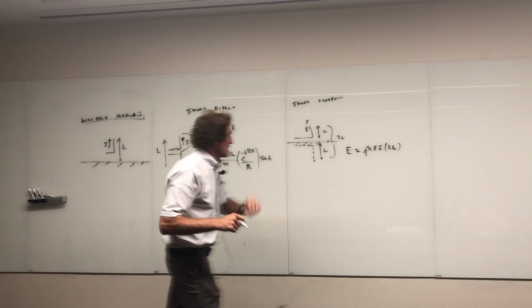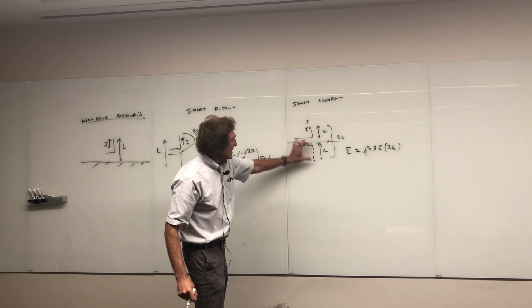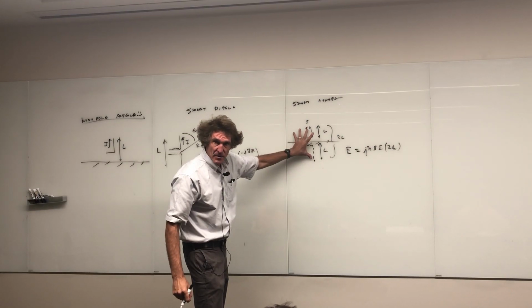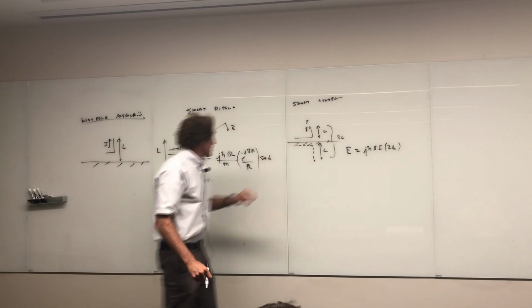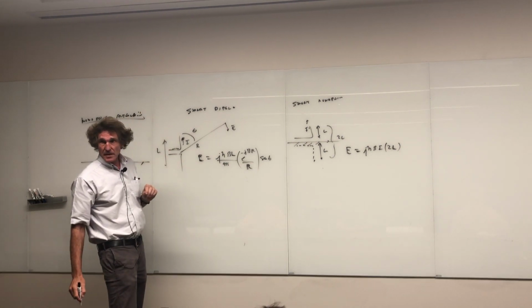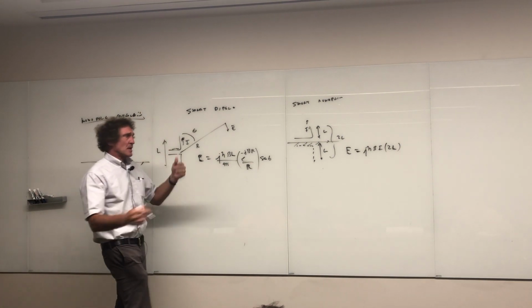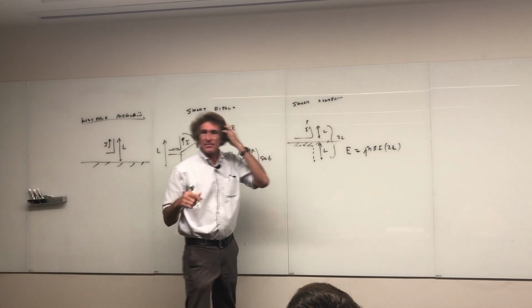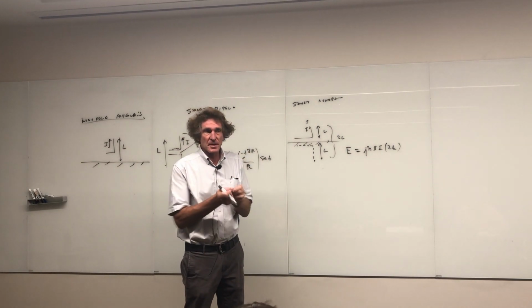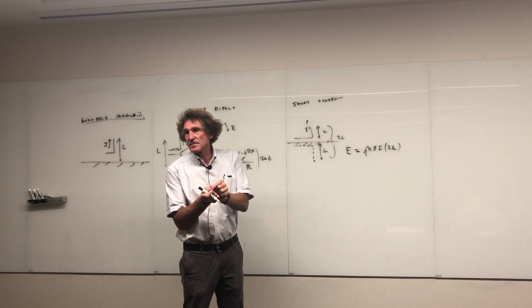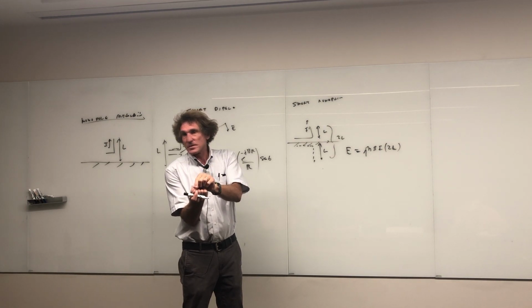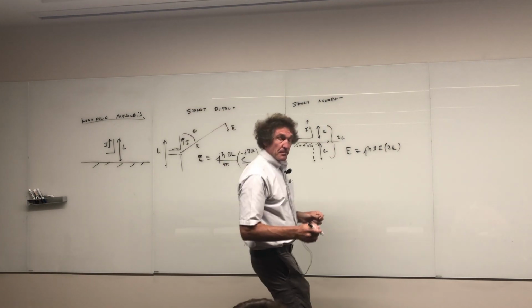It's the length of the antenna, and because the monopole has an image down here, the total length is 2L. Here, the length is just L, the length of the antenna. No, that gap's infinitesimally small. Normally, they assume that when you drive an antenna, the distance between the upper and lower portion is infinitesimal.